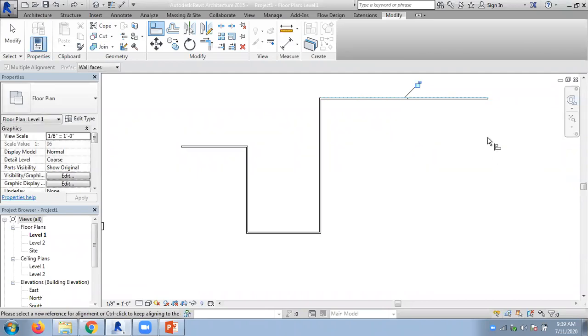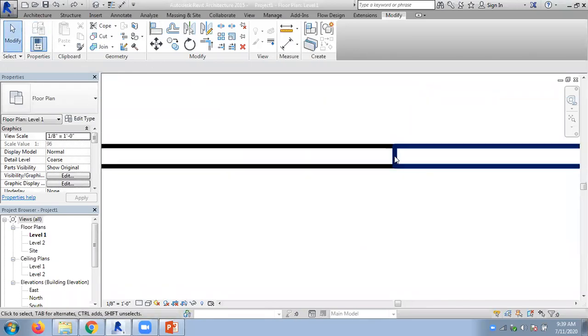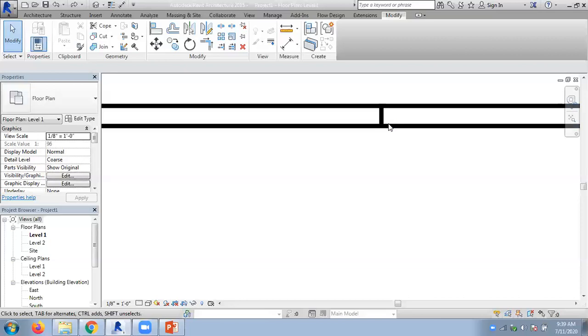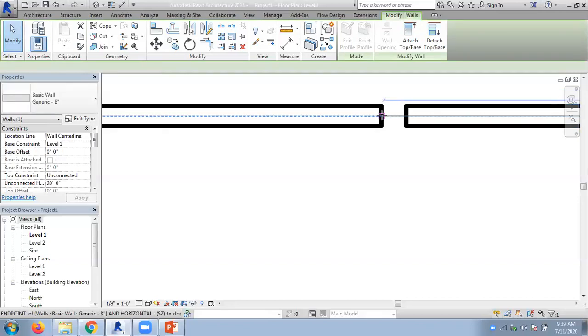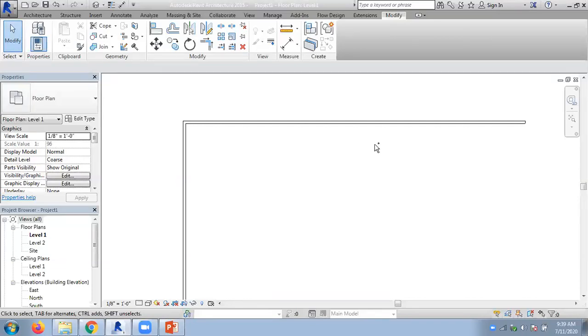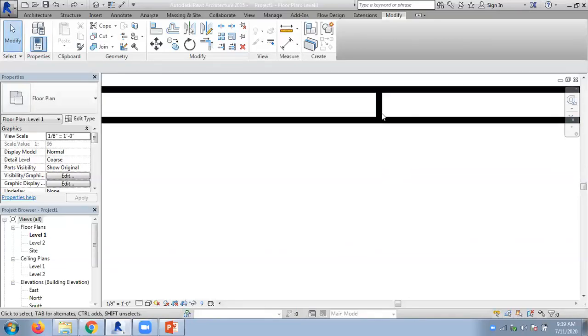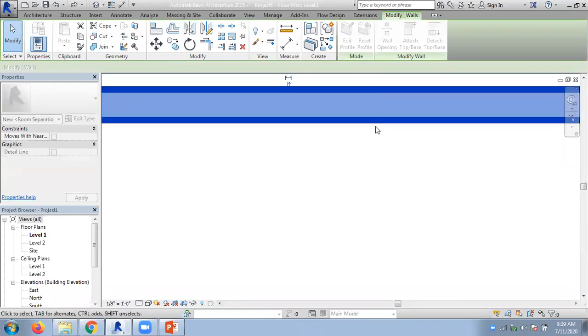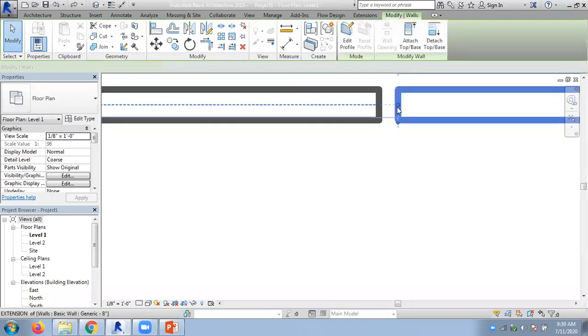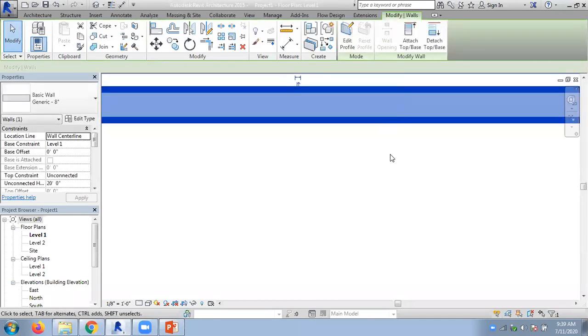Now the error vanishes. Now you can get the alignment. But here you can see a joint happens here. This is not a single wall. So there's a joint. How can I merge this? One way of merging is just to take it out and merge it like this. This is the easiest way of merging a wall. So I'll undo this. This is the result we have. You can take it inside, or just take it out like this and again join like this.